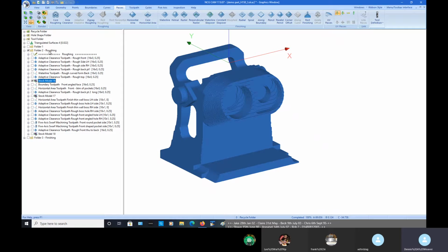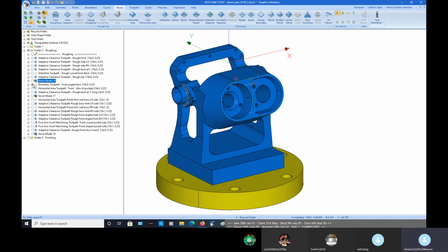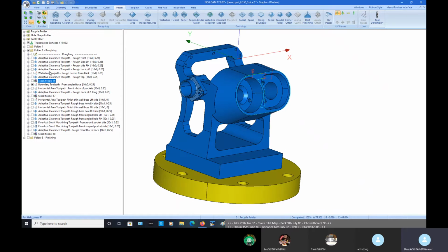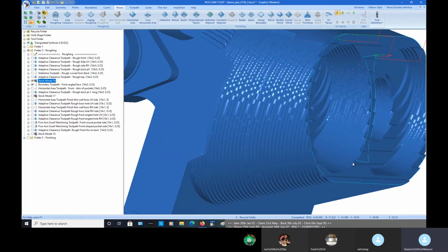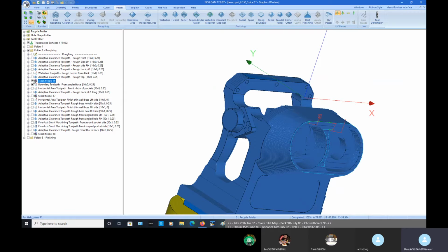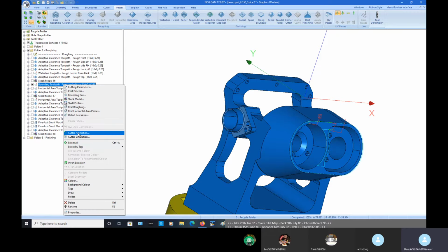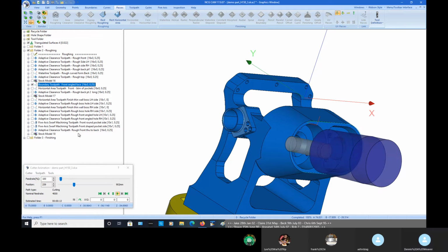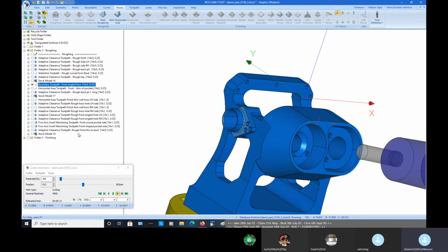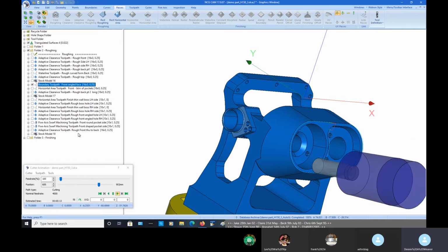So further roughing. The front face, if we look at this, the front face, as you'll see, is stepped. So a toolpath has gone in here now in order to machine the front face, to flatten it down. It goes around the outside of the perimeter and then comes back in to do the inside parts.